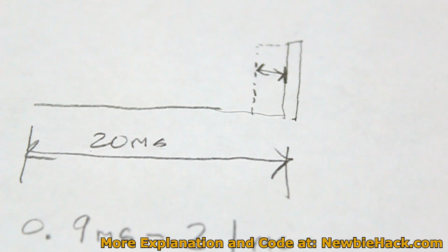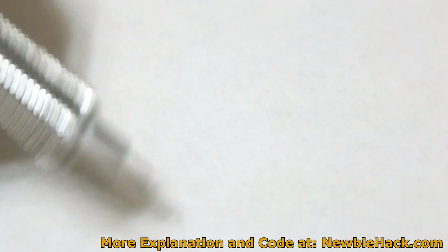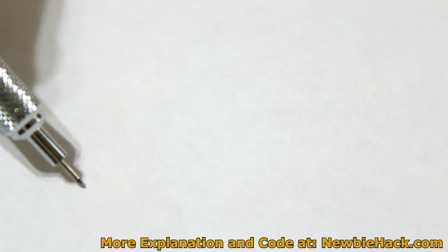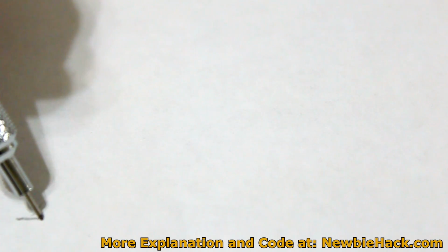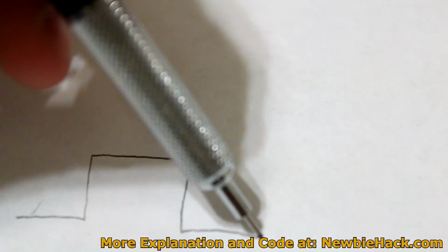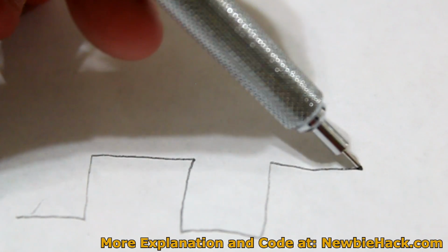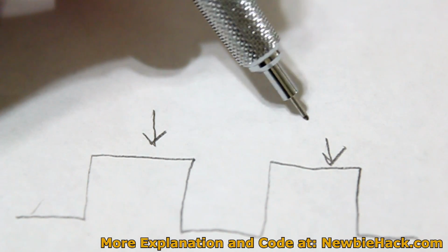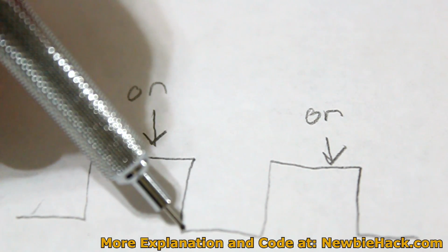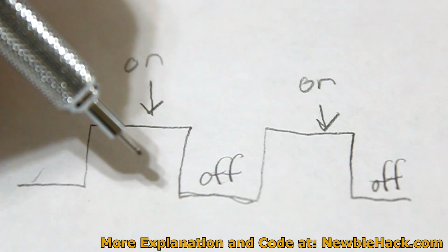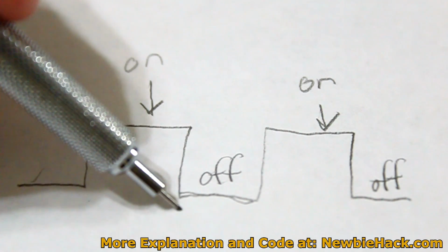So how do we create an actual PWM using the microcontroller? In the microcontroller, we're going to go back to timing. We've already created a PWM in one of our first tutorials, and that was the LED blinking. We had the microcontroller blink the LED. It was going on, and then we would turn it off. We would do this to a pin in the microcontroller, on and then off. And every time it got to one of these peaks, the LED would be on. And every time it was at 0 volts, the LED would be off. And we passively created a PWM without even knowing it.